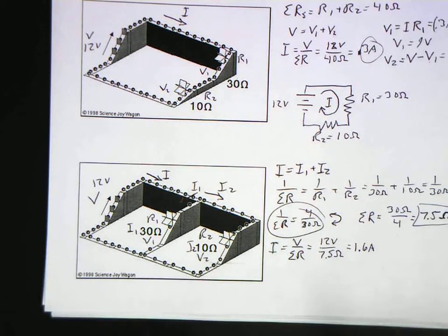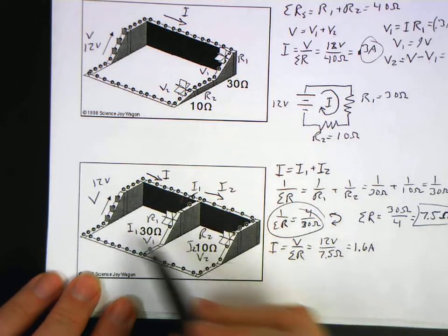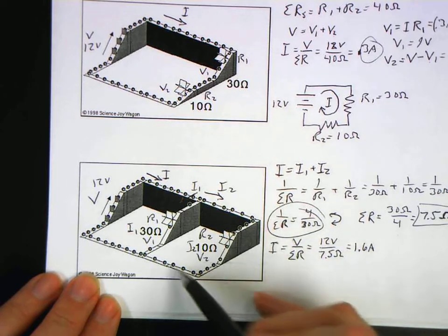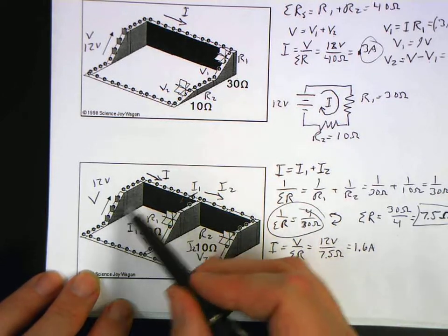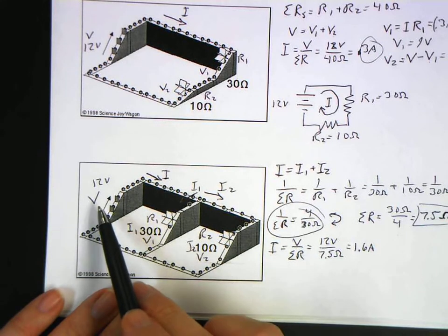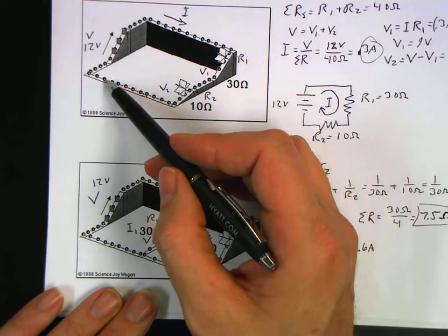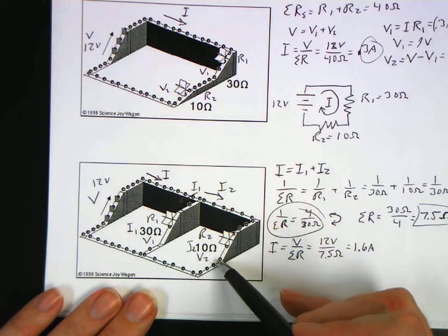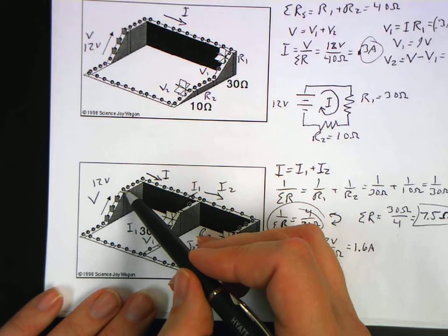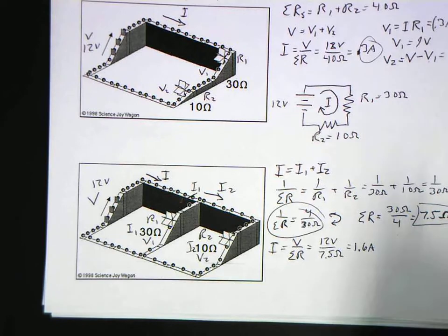Now, here's an important thing. Here's the top floor, here's the bottom floor. Notice the tops of each of these slides hits the top floor, they all end up on the bottom floor. That means they've all got the same voltage as the battery. In a series circuit, everybody has the same current. In a parallel circuit, everybody gets the same voltage, because this has a straight line back to the positive terminal, so does this. This has a straight line to the negative terminal, so does that one.